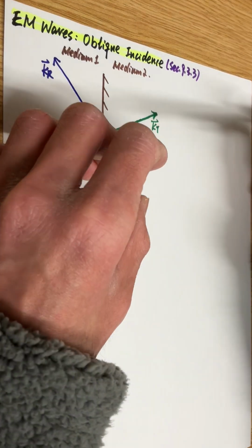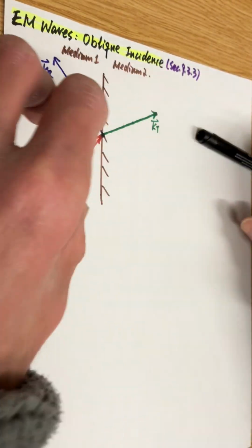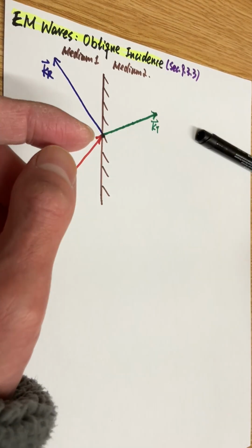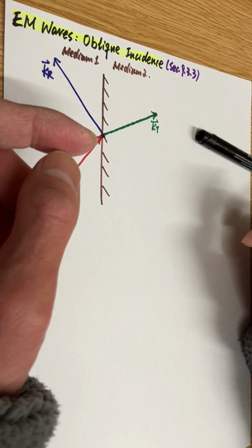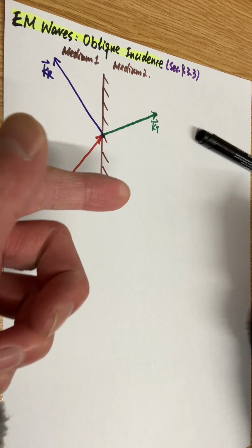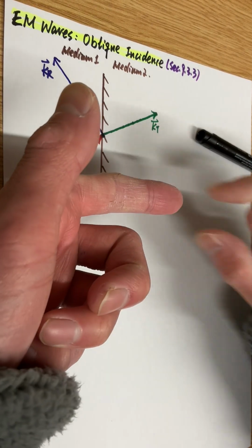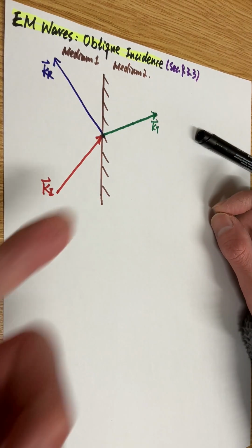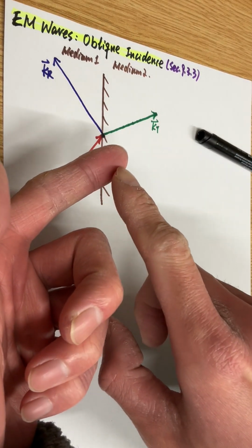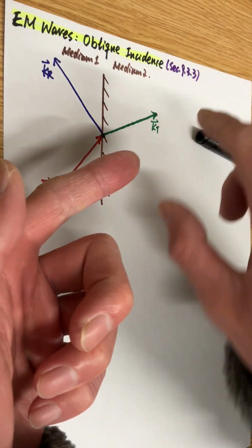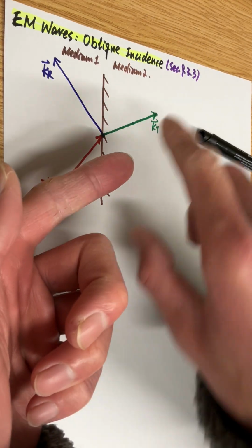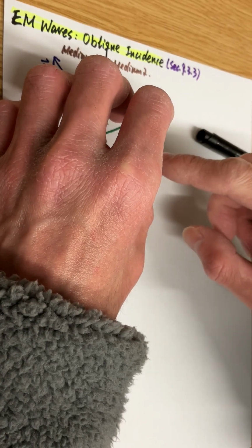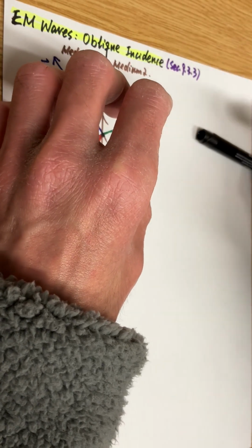We first need to, we have a fiber. We first need to get light in, and then we need to ensure that light would propagate down the fiber, down the wire. But it's not like shooting a bullet into the fiber and then it just goes straight down. It's not like that. We need to find the angle that we have the total transmission. So light does get in the medium. And then inside the medium, we need to design in a way that we have total internal reflection.